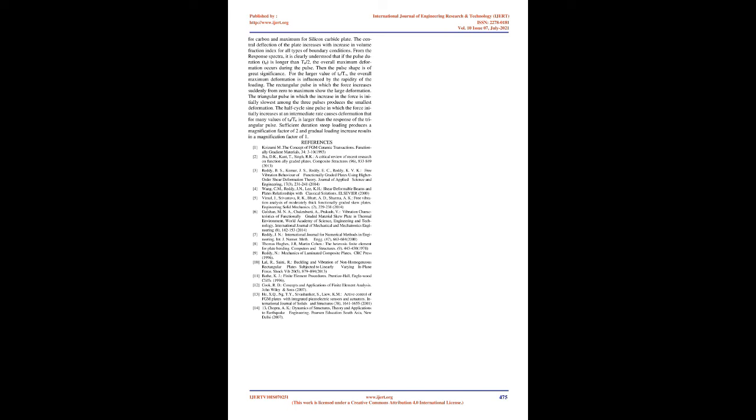4. Conclusions. In the present study, an FE solution is obtained for free and forced vibration analysis of FG plates using heterosis element. The analysis is carried out by developing a computer program in Matlab. A 9-noded heterosis element is used to model the FGM plate. The heterosis element exhibits improved characteristics as compared to the 8-noded serendipity and 9-noded Lagrange elements. It offers a high level of accuracy for extremely thin plate configurations.